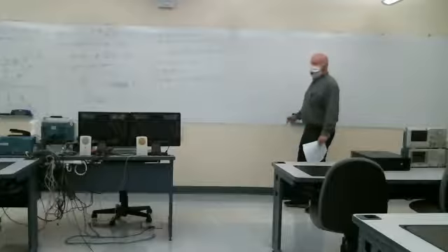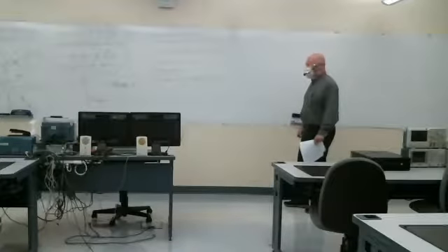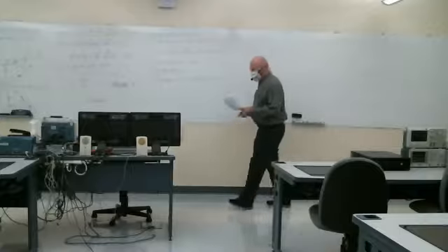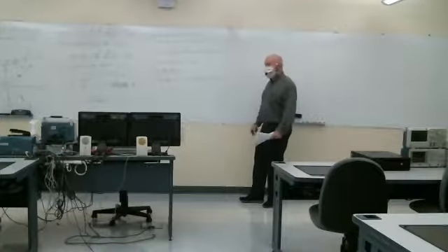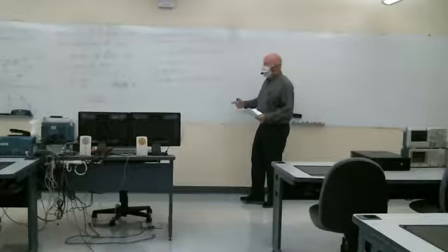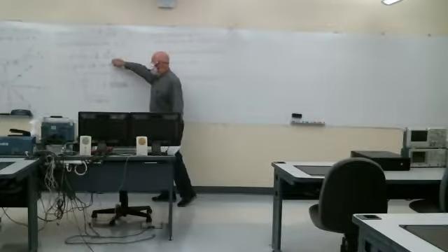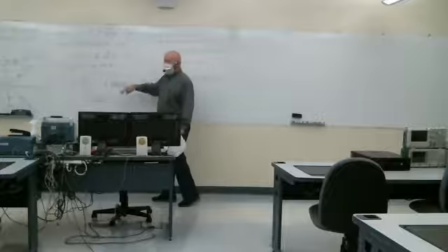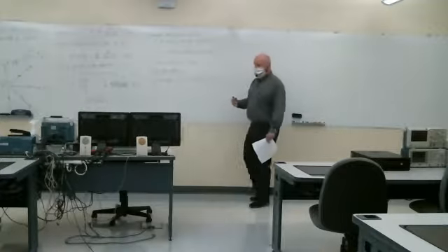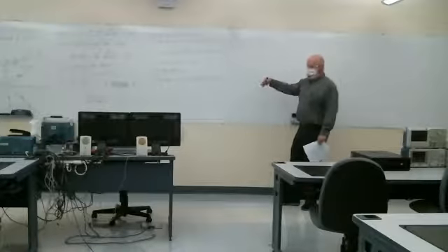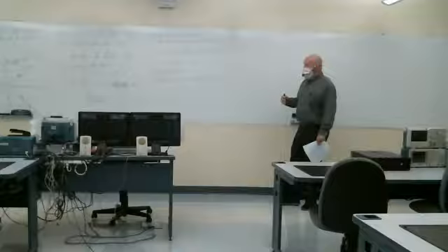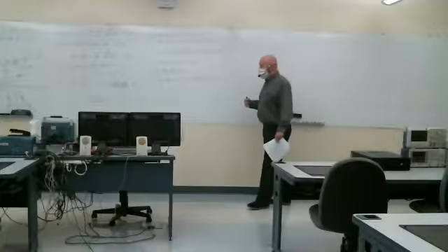We'll see how this is actually related to the speed of light a little bit later on. In any other material, the permittivity can be slightly higher, sometimes much higher, than the permittivity of free space. And with a stronger permittivity, our electric field intensity is going to decrease, because it's in the denominator here. So you'll typically have your largest electric field intensities in free space, and in dielectric material the electric field intensity will actually decrease.